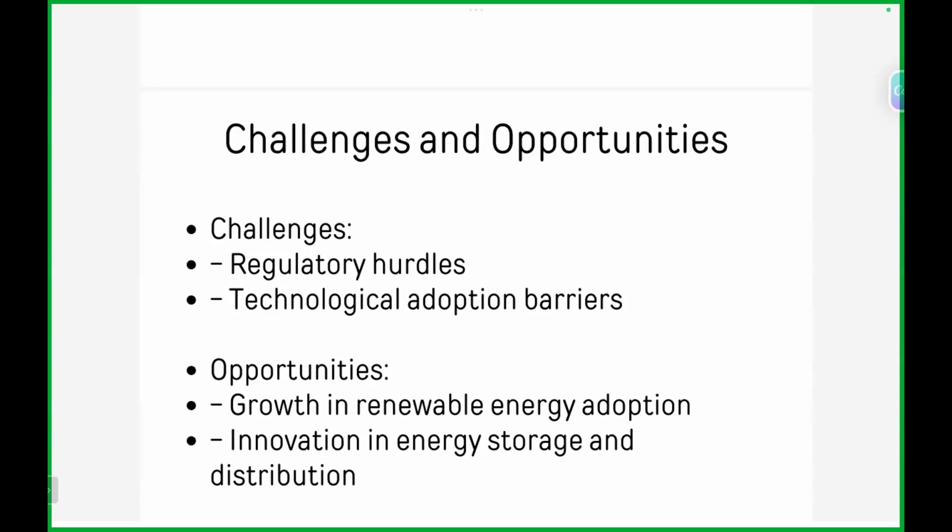And the second thing is that at the same time we are implementing renewable energy systems everywhere, but the tragedy is that we don't have control over harmonics. Since it is a variable generating energy source, you are not in control of giving constant energy. You will be facing a lot of grid instability by adopting renewable energy. So that's the reason for having renewable energy along with real-time monitoring as well, and SVGs, static var generators, to be implemented along with renewable energy to have better grid stability.